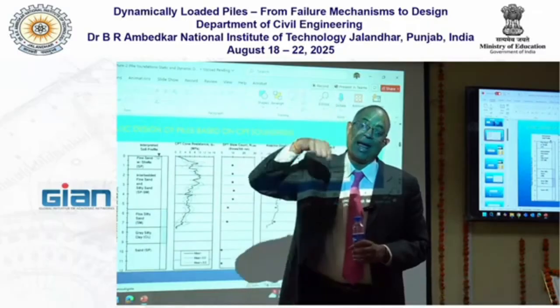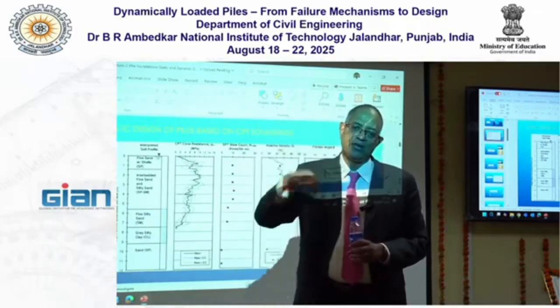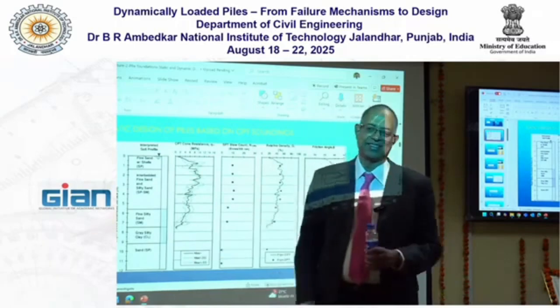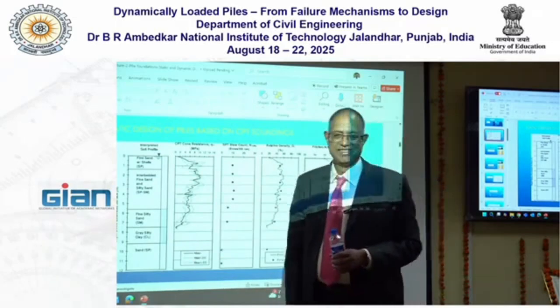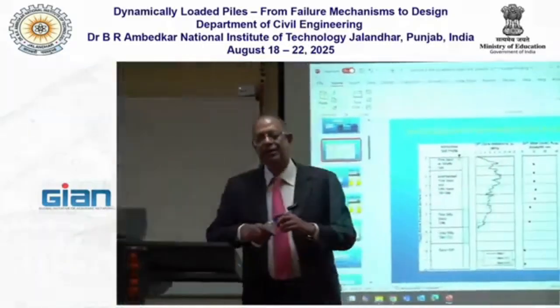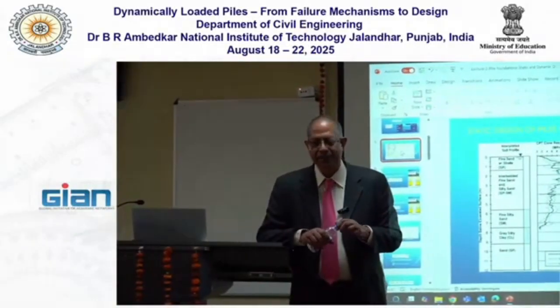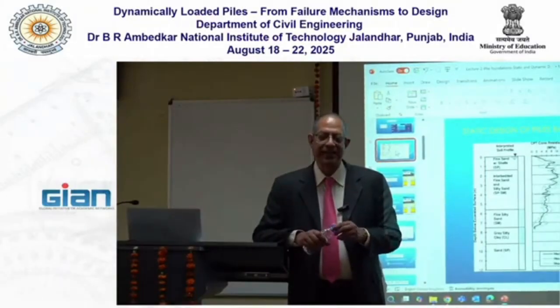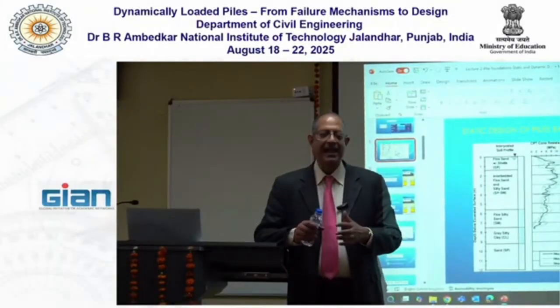So yeah, that is why they try to average along. That is to account for the length direction along the driving direction. What you are saying is along the lateral direction. So you need both. But the good thing is if it is doing that for the CPT, it will do the same when you drive the pile. That is the assumption, right? It's just a scaled up version of that.